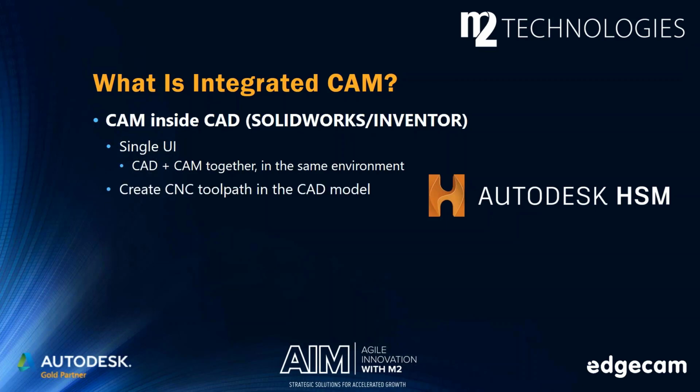Obviously, CAM's used to create CNC toolpath, and in the case of the integrated systems such as Autodesk HSM, the CAM toolpath is added directly into the CAD model. This allows for model associativity, which means that when there's a design change, the toolpath that's already in that file can be quickly updated to suit the latest variant or dimensions of that CAD model. So in the same way that, say, a sketch or an assembly is associative to model changes, the toolpath in that CAD model also would be.